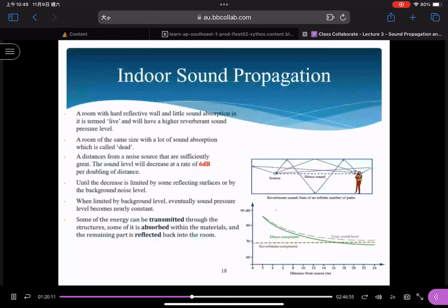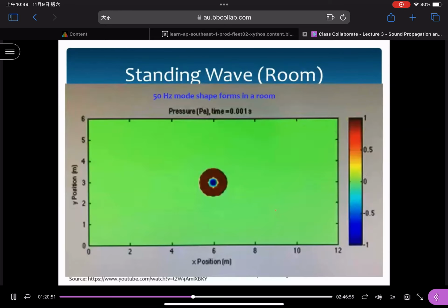In this figure, we just consider two components. Under steady state, the reverberation effect dominates the direct field. Correct? Because the longer the distance, the lower the direct field, until the total level is almost the same as the reverberation level. So at steady state, we just need to consider the reverberation component. I will demonstrate an example to you later on.